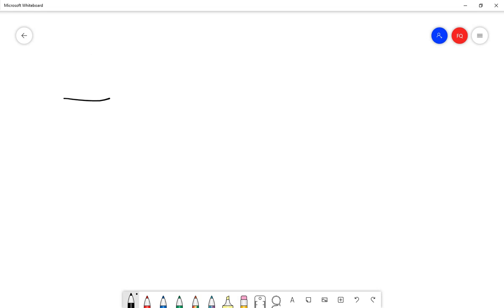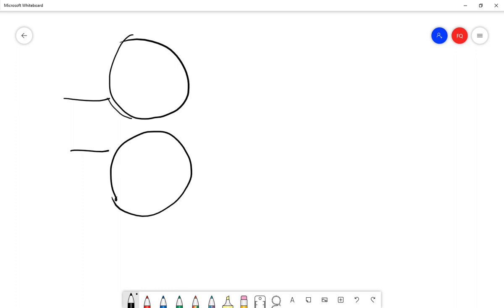What I said was that we have an initial roll, and the material is going out like this. Initially, for example, we have 20 millimeters and we want to get a sheet of 5 millimeter thickness. This is just an example. We have to reduce 15 millimeters of thickness, which is quite a lot.